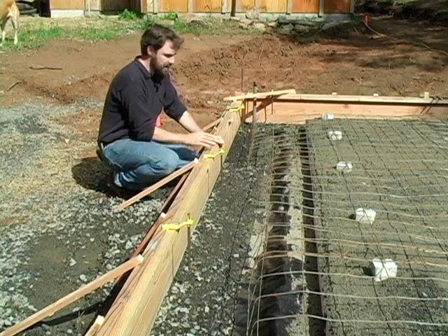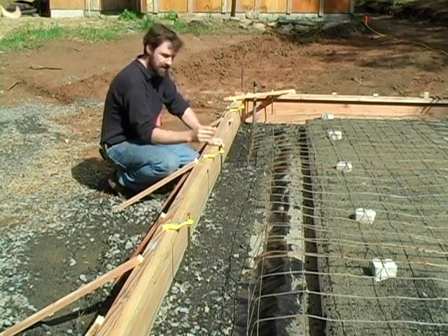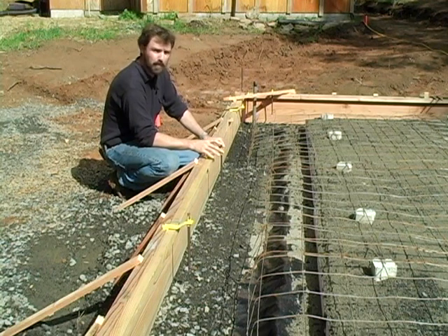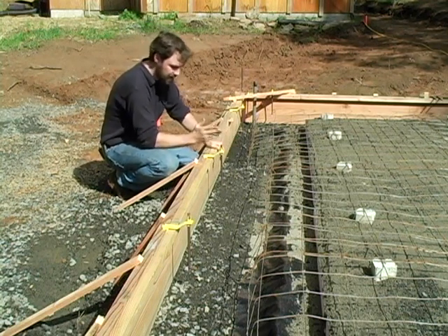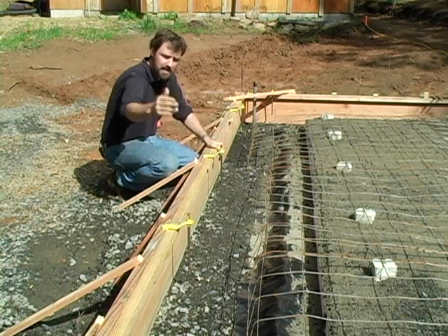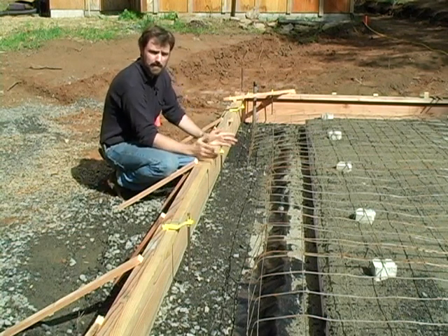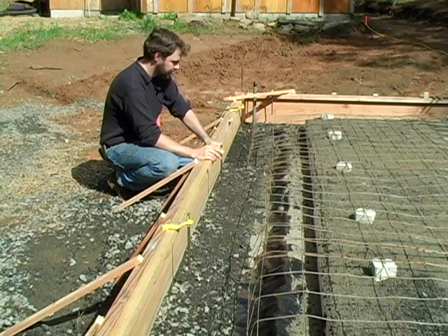The reason I do this is that in my code, and most likely in your jurisdiction as well, you have to have an anchor bolt within 1 foot of the end of your board. So you have to mark those all out. Then you can start with your end pieces and then find the centers based on what the local distance between bolts is in your area.